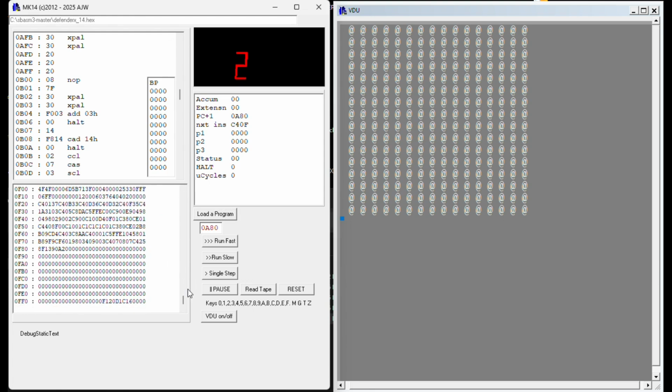You might have seen some mirrors shooting past. If I go to 880, here is the first 128 bytes of the Defender program. Nothing at 900 because that's not repeated. 880, and then we keep going and we see it at A80, and that concatenates with the B0 here. If I keep going down the memory space, C80, there's another mirror.